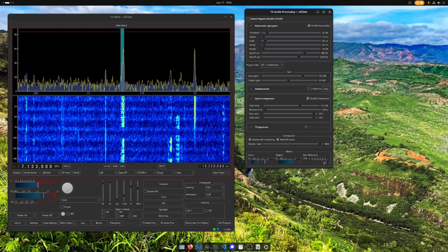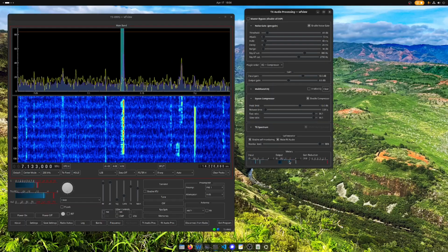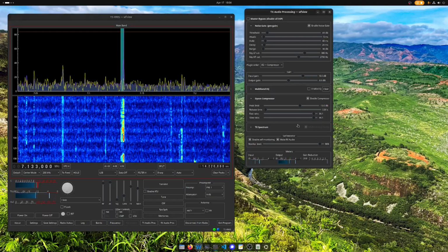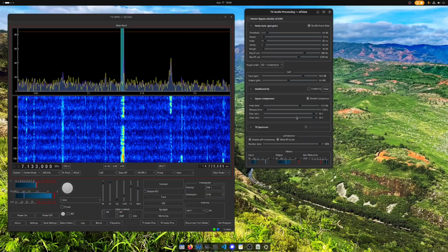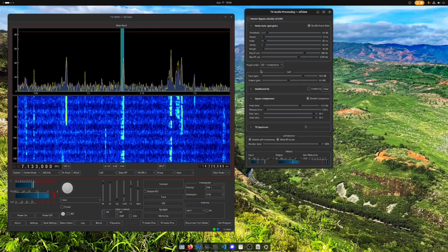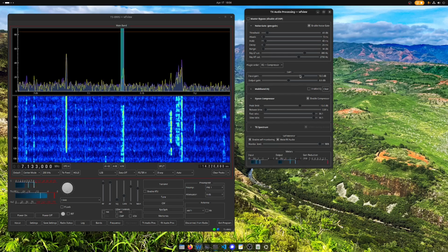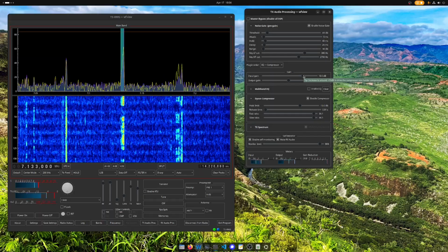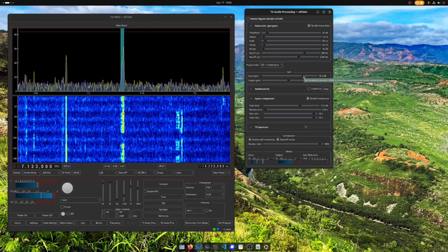You can see the gain reduction down here metered and the output level. The output level is also shown over here where we show the radio level. Test, test, 1, 2, W6EL testing. And if you'll notice, I've increased the input gain to 10 dB. And that really helps drive the compressor into harder compression, which I think sounds really nice on the air.